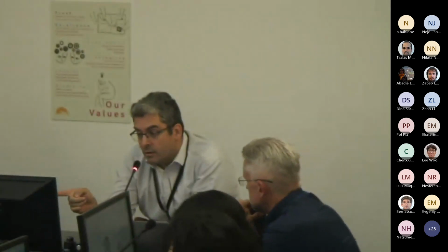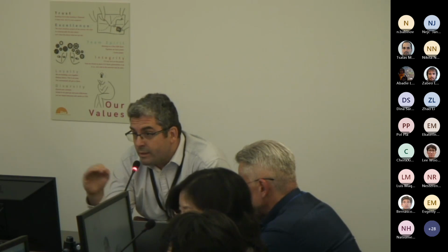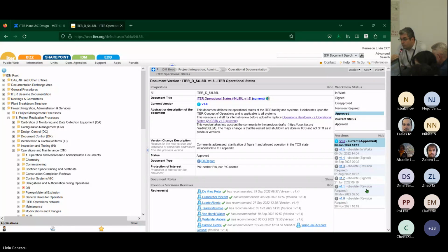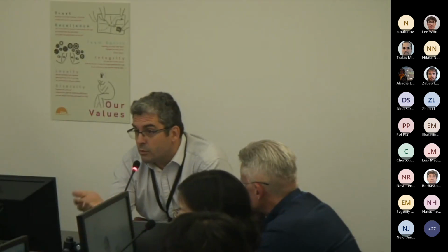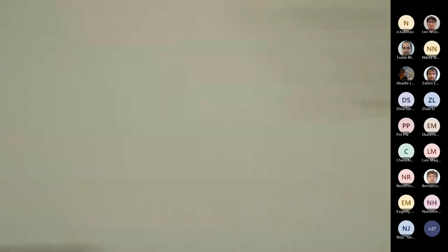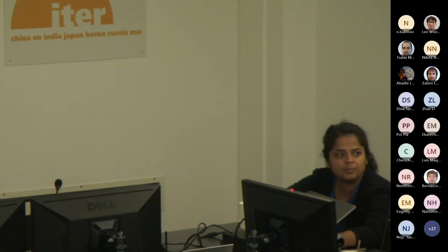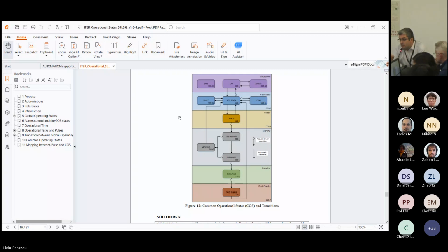I think in the diagram, we cannot see it now, but I think in the diagram from ready to not ready is not a request-driven transition, right? I think that's the case. So ready means that if SUP says countdown starts, you're ready for countdown. If you're not ready for countdown because the safety interlock says you're not ready, you cannot report to SUP that you're ready. That's all. Yeah, my question was more when we are ready and if there is a trip, which I think Alex answered. Thank you.